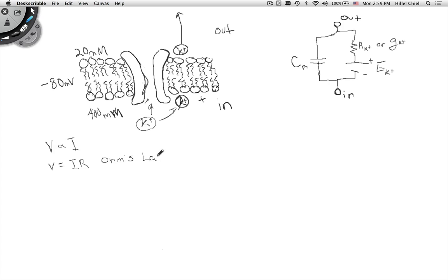Okay. And let me just say this again. If resistance is very, very high for a given voltage, how much current do you get? If resistance is high for a given voltage, then you have a low current. Exactly. And if the resistance is low? Then you have a high current. Exactly. The way you can think about it is if this is like a pipe that lets things flow through it. If it's very narrow, it has a very high resistance, and it's hard to flow through it, so you're not going to get much flow or current. And if it's very broad, then you can have a lot of things flowing through it. And so for the same voltage, you'll get a much higher current flowing through it. Okay. That's V equals IR.